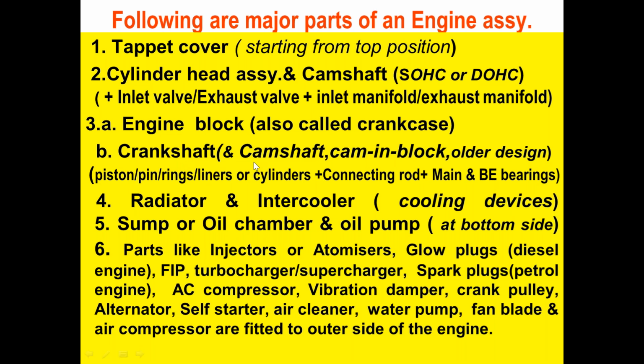Again, I have mentioned the camshaft here because in earlier designs, the camshaft was in the block position. Now it has gone to the cylinder head, overhead. So there is a change in design from earlier to the latest. The engine block also contains the piston, pin, rings, liners or cylinders, connecting rod, plus main bearing and big end bearings. Radiator and intercooler are the cooling devices.